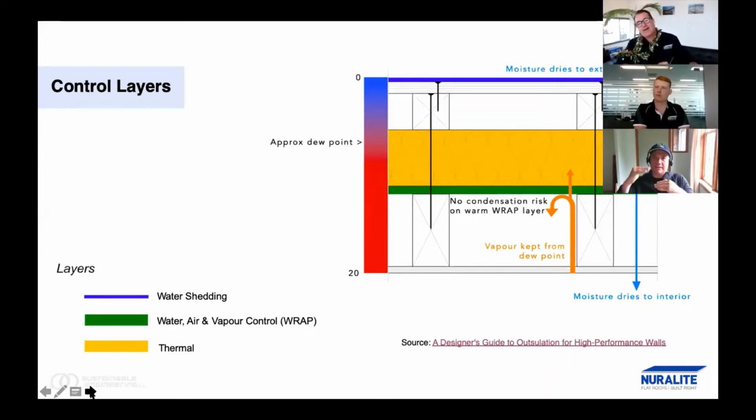And the more insulation we put in, think about when you have a wall that's better insulated, you're saving money because you're not putting as much energy through that wall or roof. And because you're putting less energy through it, there's less drying potential that occurs in that insulation layer because it's thicker. So the same amount of moisture that used to be okay, like you got away with it before, you didn't actually get away with it. It was actually good design. Now, if you don't have better air control, you're going to have moisture problems you didn't have before.